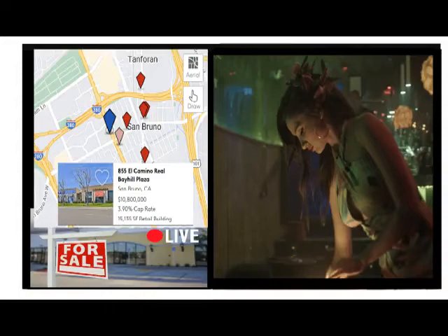Basic roof styles were illustrated in Figure 14.1. The roof structure is shown in Figure 14.5. Roofs are formed by rafters, sheathing, and a finishing material. The rafters meet at the ridge board, the highest point of construction of a frame building. Sheathing is usually plywood. Spaced sheathing of 1 inch by 4 inch boards is used for a wood shake or shingle roof to allow better air circulation. A heavy waterproof paper called building paper goes over the sheathing first. Putting an insulating blanket on a water heater can save energy and money.